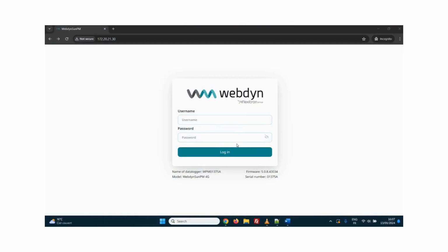Welcome to the video presentation of the new web interface of the WebdynSunPM. To access the web interface of your gateway, simply type the IP address inside a web browser. By doing so, you will arrive on the login page. The default credentials for the gateway are user hi and hi.